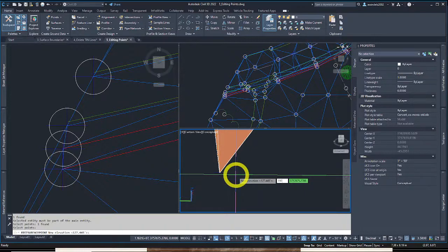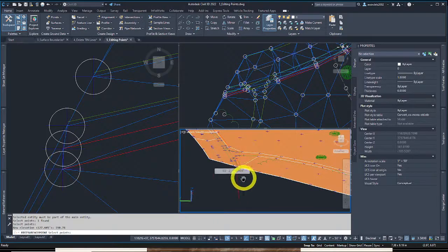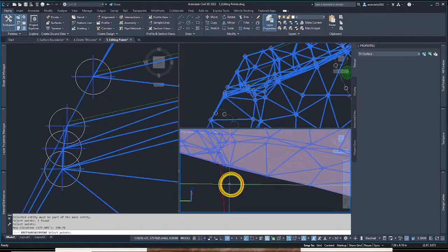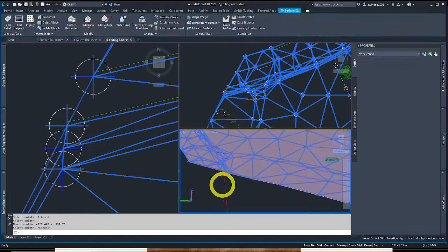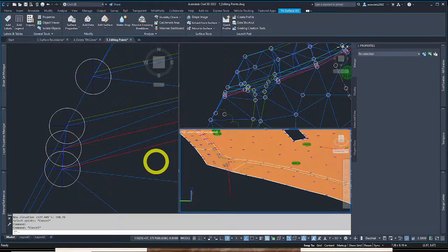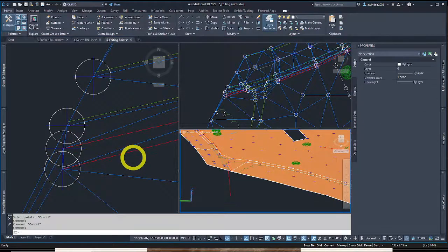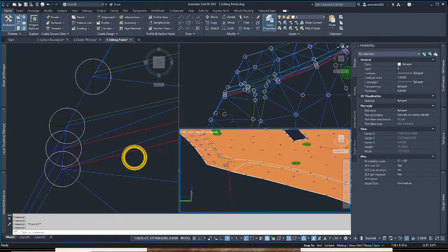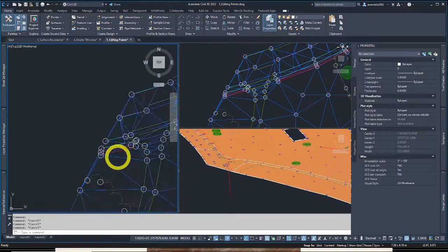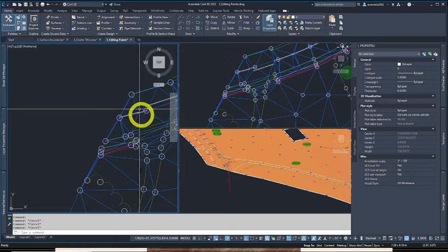And we're gonna say 190.76. Hit enter. It changed the surface to a more valid point. Now notice how it left the survey figure behind. It might be prudent to change that survey figure now. A lot of times in a different workflow, our 2D and 3D stuff would already be fixed. If we're using survey figures, that would remain. So that's fixing that.